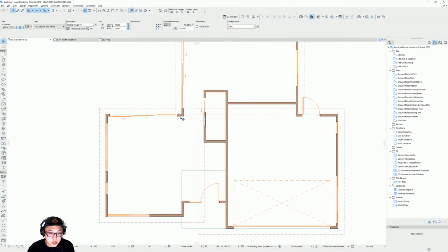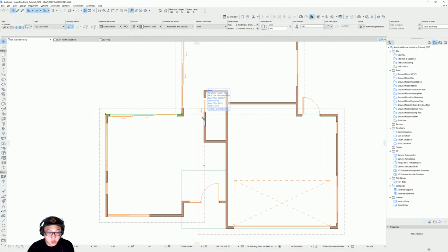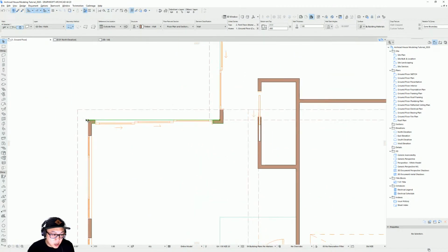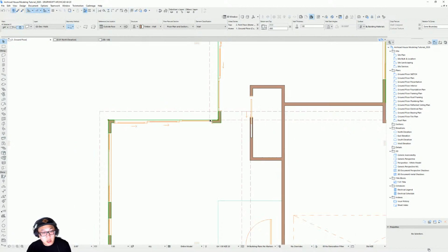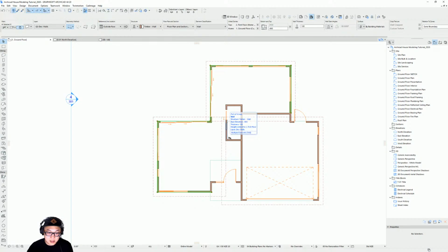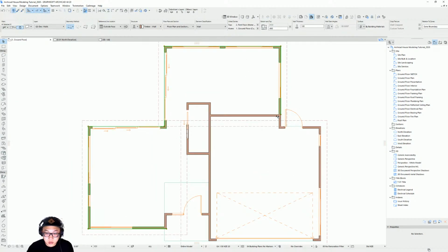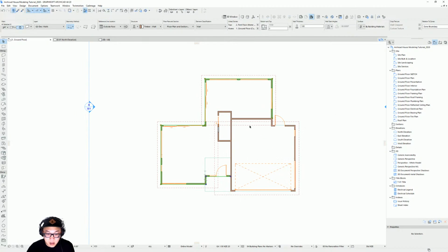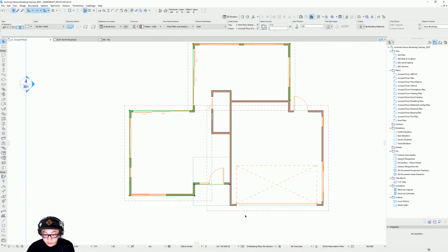And now what you want to do is to select the walls, the exterior walls. So right now you see I've selected that wall, but you see that green line and this dot, it means that it's part of a group. If you press Alt G, it will select all the elements that are within that group. So those ones, and I think I'm going to select these two as well. Because I want to have different cladding on this one.